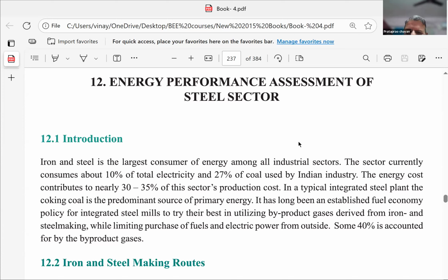This is so far as the boiler is concerned. Okay, one unit's performance we have seen. But this 15%, is it entirely going to the waste gas, or is it excess air supplied, or the individual component efficiency that we are losing, isn't it? So you have to find the breakup of the losses.